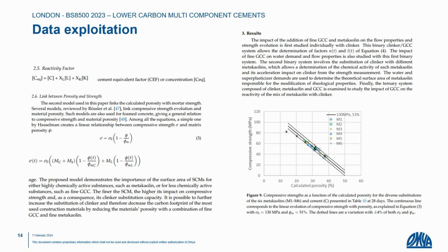The second point, and really important point, is we need to introduce the question of flowability and compatibility with superplasticizer. Because the engineer knows the compatibility of cement and superplasticizer, but the compatibility of superplasticizer and SCM is totally unknown or not declared by the user, because the engineer has to play with it after.